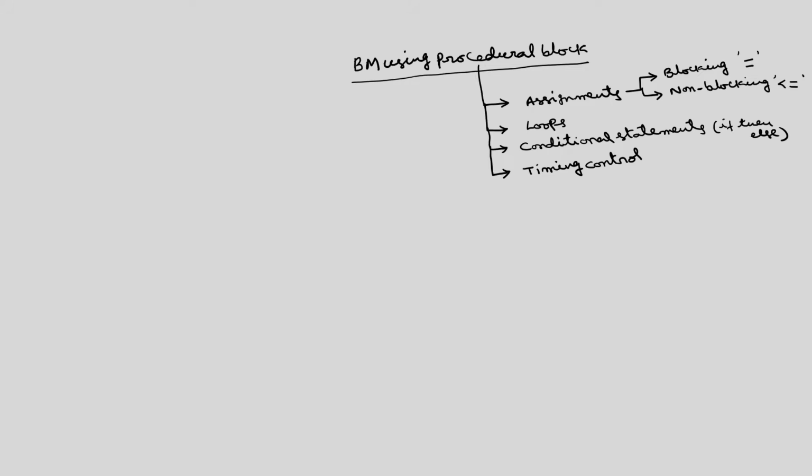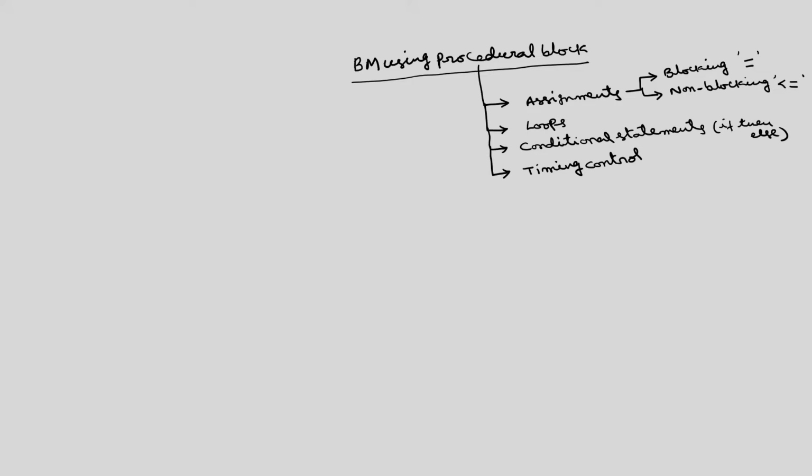Whereas in case of non-blocking, we can execute all the statements simultaneously. One of the important features in the procedural assignment is that the target output must be register type.